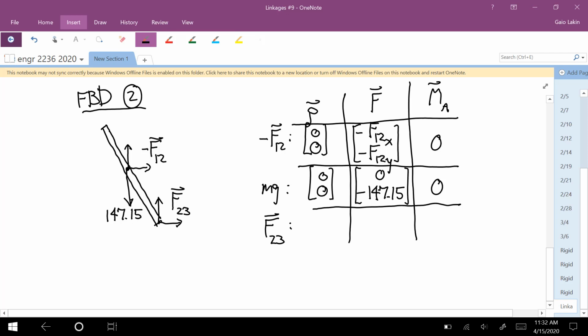Okay, so what's that? Well, you can think of that, it's perpendicular to that last member. So you can think of it as the vector that's going from the center to that point at the bottom right is 30, the angle we had before, which is 36.87 minus 90. So that gives us our angle. And then it's times the length from there, which is 0.9.